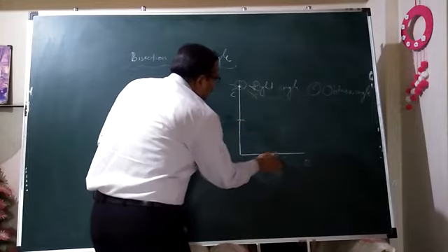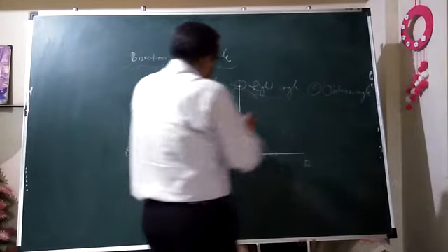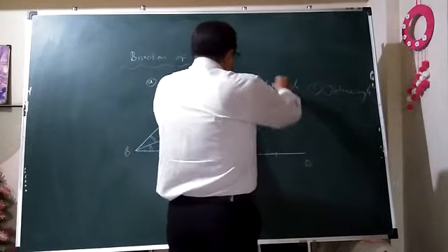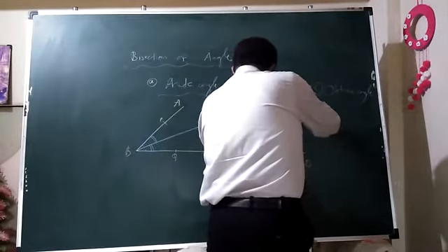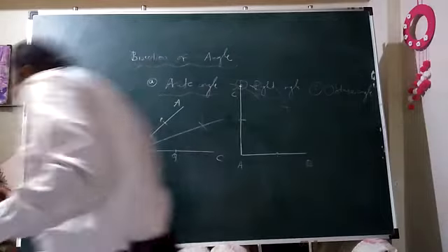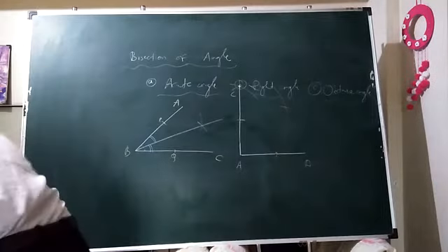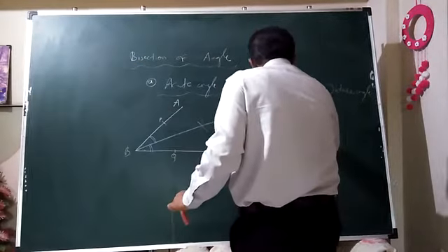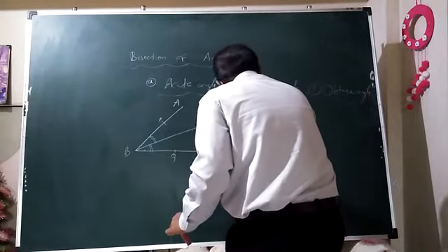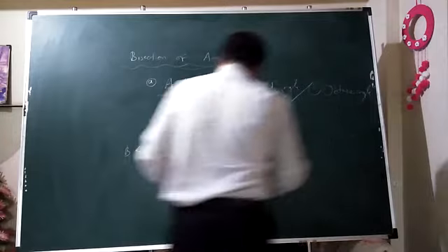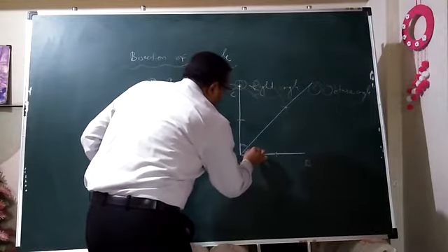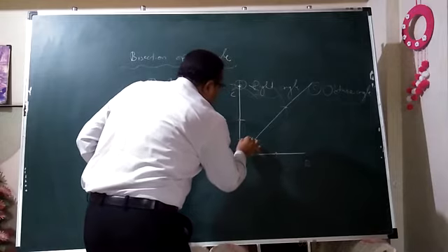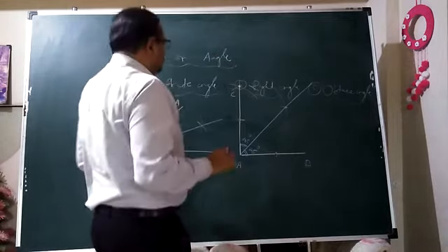First of all, highlight, make them bold points, and now you can change the distance and get two intersecting arcs in the space in this way, with the same radius without disturbing the distance between both the legs. Now that intersecting point you have to connect with A and extend it up. So naturally this angle and this angle both will be carrying the same 45-degree angle. You can check it by using a protractor.